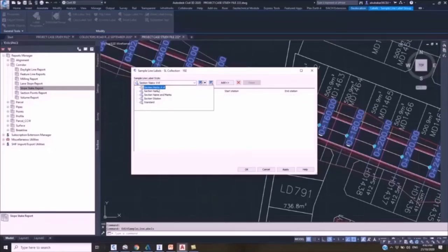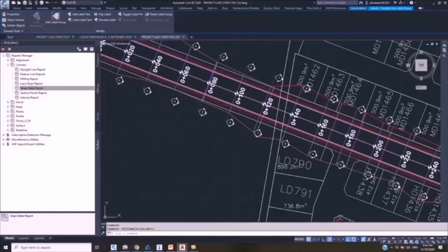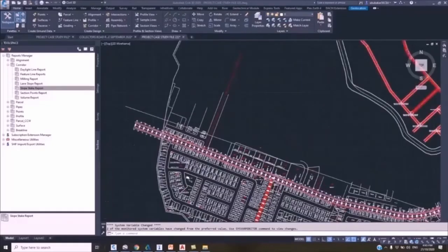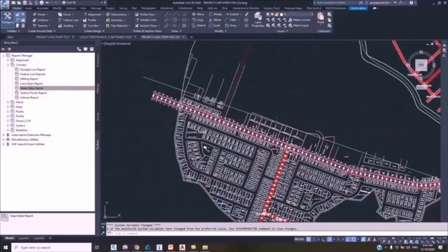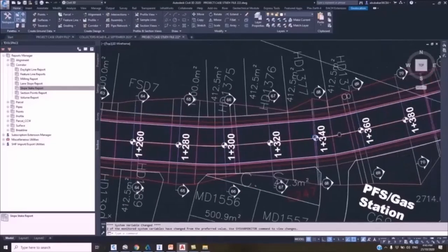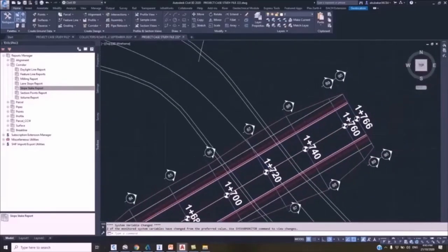I need to extract the section mark to define my cutting of the sections at interval so that it can display for me all the criteria, all the things that I needed to coordinate for this workflow. So now from the cross sections I observe, I can now check out the information for this. I've defined that, so it has been clearly stated. So now I have the sections cut at 20 meters interval along that corridor as defined. You can see the information is already there.